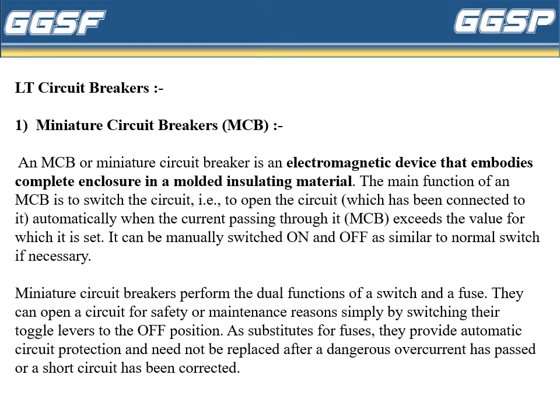They can open a circuit for safety or maintenance reasons simply by switching their toggle levers to the off position. As substitutes for fuses, they provide automatic circuit protection and need not be replaced after a dangerous overcurrent has passed or a short circuit has been corrected.